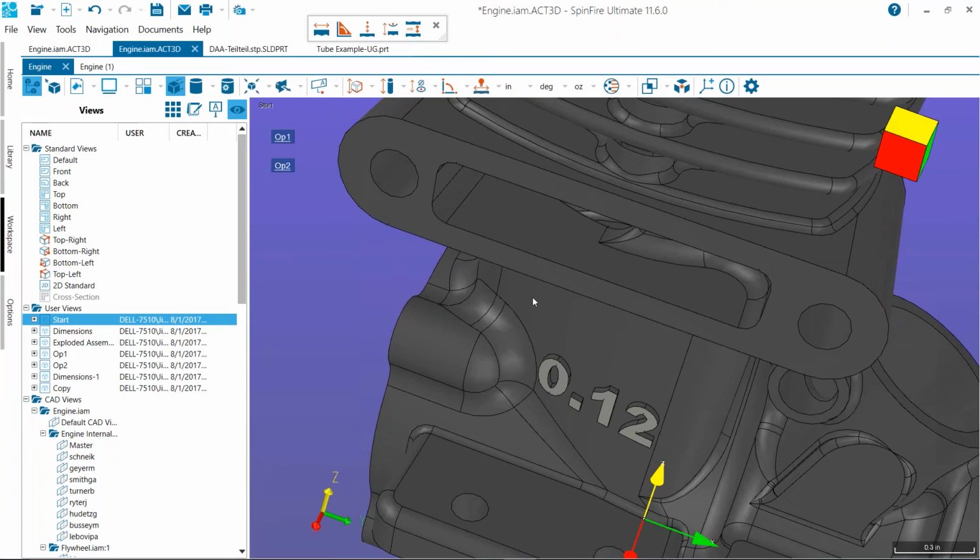Good point. Yeah. And if they're not continuous, if the file that was imported, depending on what it is, tolerances build up even within the CAD file. You go from CATIA to STEP to NX, you have these tolerances that get built up, and it could be that there's a slight gap between those two edges that the software is not going to chain across.